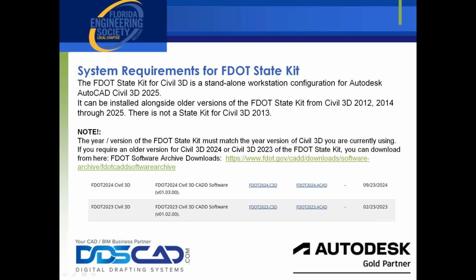Now, we have a rule. The version of AutoCAD Civil 3D that you're using requires you to download the version of the Civil 3D state kit that matches it. So if you're using Civil 3D 2025, then you must use the FDOT 2025 Civil 3D state kit. Okay, that's the one that you must install.